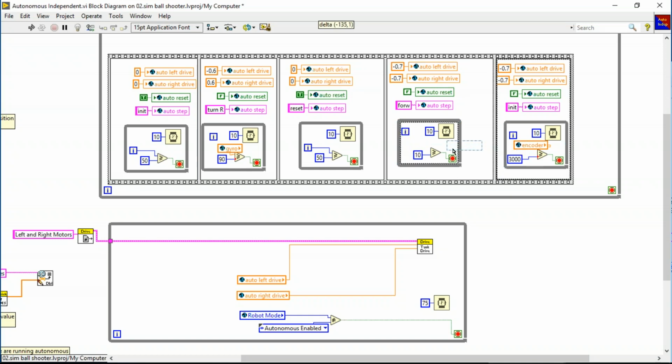So the way you get rid of broken lines is Control B. So Control B will get rid of all that stuff. And I want this to be 3,000 down here. Sorry for messing that up, but it just shows you got to be careful even if you've been doing this 100 times.